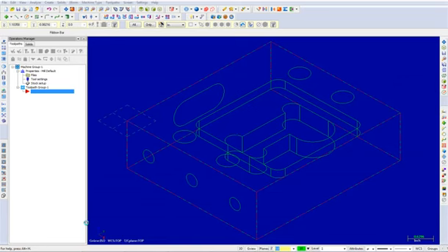In this video, I will show you a 2D high-speed area mill toolpath. 2D high-speed area mill is used to machine pockets using a smooth, clean motion. Helical entries and tangent stepovers create efficient motion for your machine. Cut parameters let you control smoothing to create the best toolpath, avoiding sharp corners or direction changes.